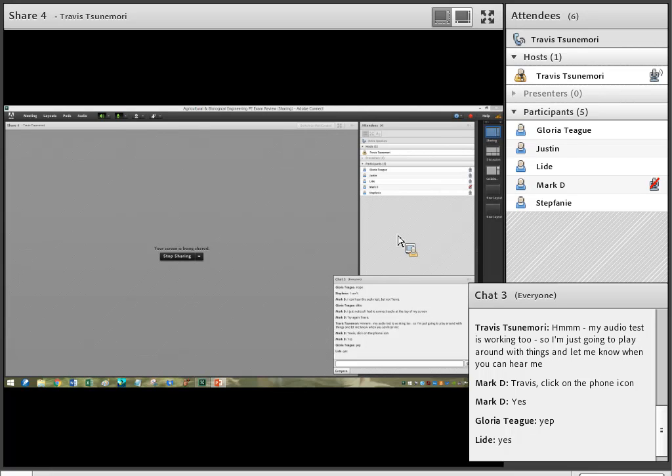Okay, so let's start off with conservation of mass. It's basically that if the rate of flow is constant at any point, and there is no accumulation or depletion of fluid within the system, the principle of conservation of mass is upheld. So the mass flow rate is in kilograms per second, so m1 dot, remember the dot over it is telling us that it's a rate. If the dot's missing, then it's just a mass. And this is in a system. So we're looking at a system of pipes or flows.